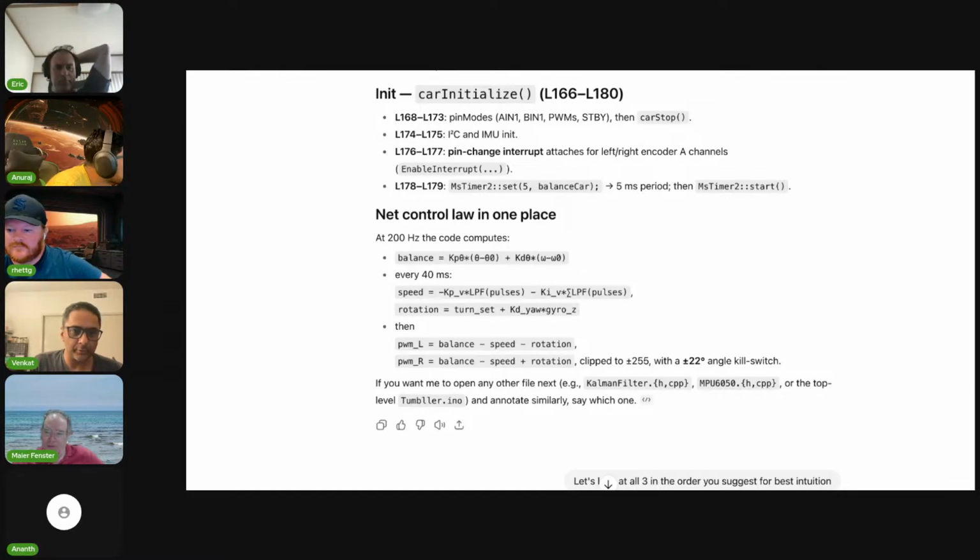And the Elegoo code does not contain any parameters except the controller gains. So that's kind of annoying. We're going to have to do some measurements to figure out masses and inertias and stuff like that, unless it's buried somewhere in the documentation. But yeah, all that standard analysis, sensitivity analysis, transient peaks, all that stuff is tedious, standard control design analysis.